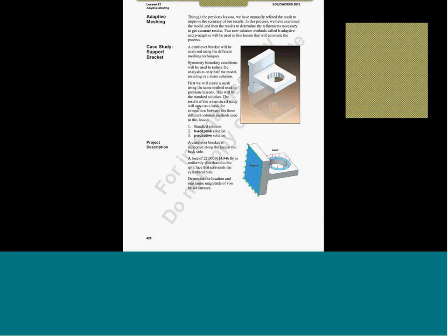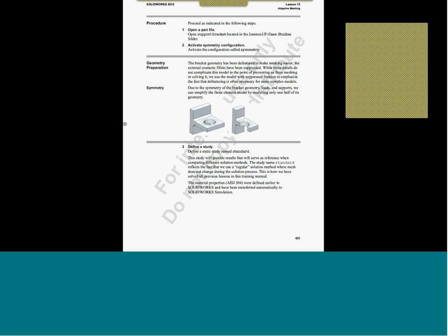Okay, so a simple model. Yesterday, as we discussed, we have draft quality elements with linear interpolation of results between two end nodes. Then we have high quality elements with a mid-side node, and internal to the software we are calculating in quadratic format. Then we also have polynomial elements, or P elements, which can handle equations all the way from 2 up to the polynomial.